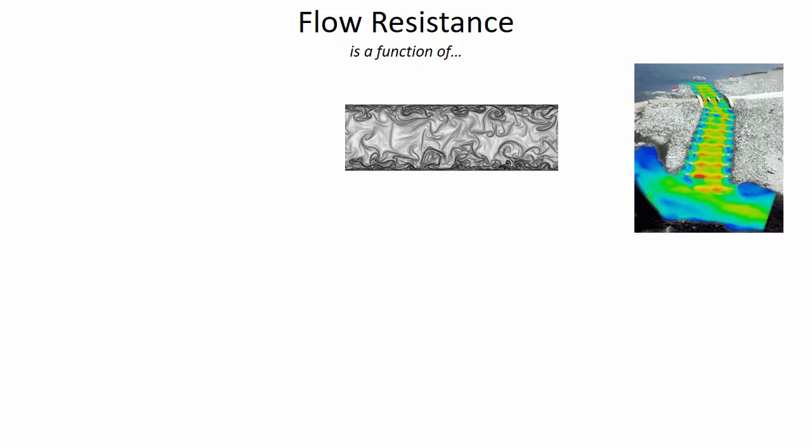Before we get to any of that complicated stuff, though, we need to revisit the idea of flow resistance. This is a cross-sectional representation of a pipe. And what it illustrates is the turbulence as the water is flowing through a pipe, and the fact that velocities are higher at the center of the pipe where there's less resistance to flow. The velocities are lower at the edge of the pipe where the influence of pipe friction is observed more directly.